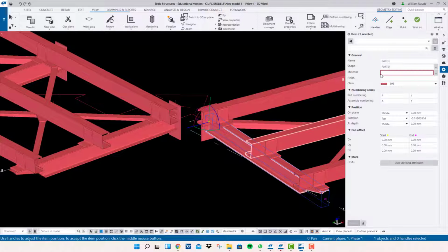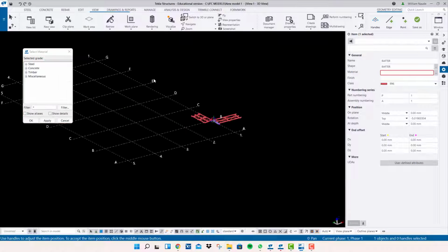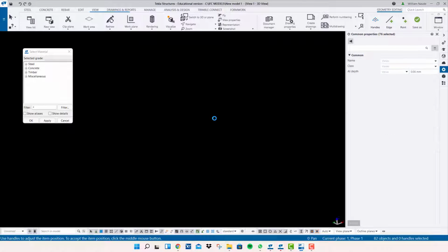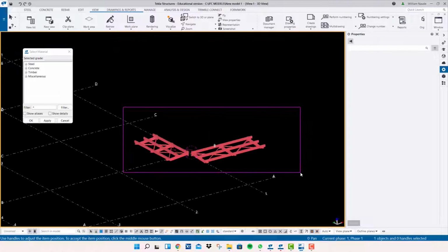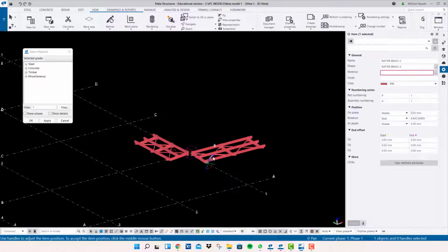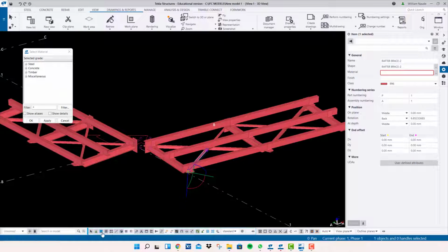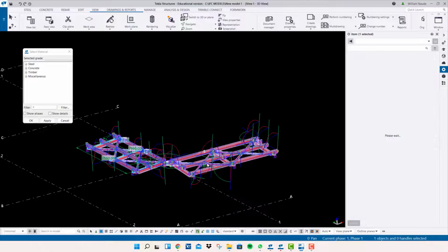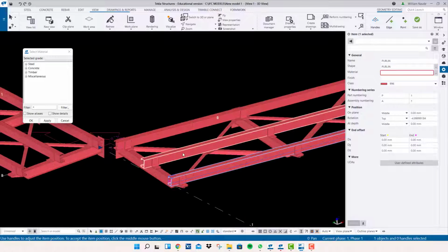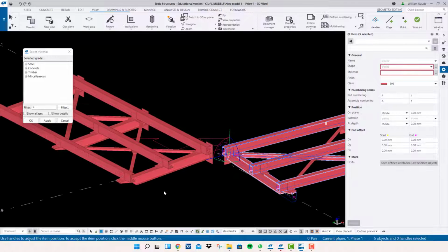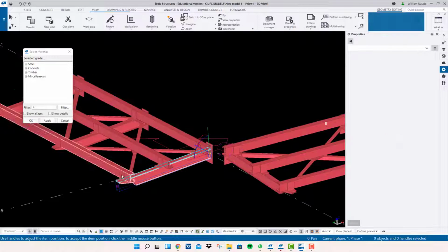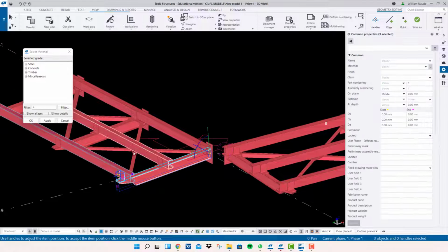So if I double click on this item, you just need to change the materials. So I'm going to highlight everything. Or rather, let's do this and choose parts. Let's highlight every part. Okay, it doesn't want to do that. Right, let's see, it picks something else up. Right, so what you have to do now is you have to say that should be S355JR and say modify.